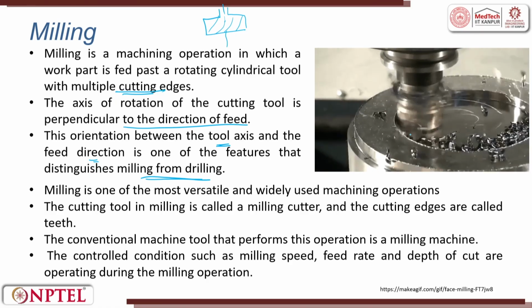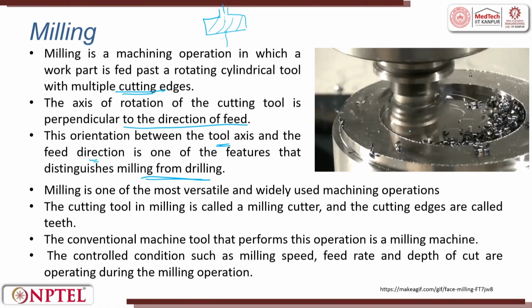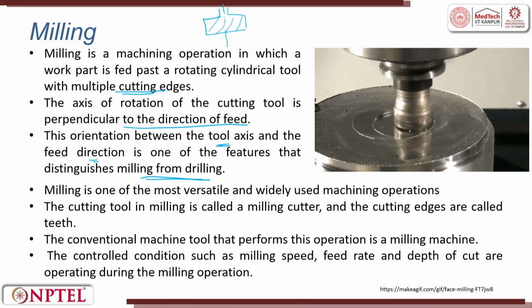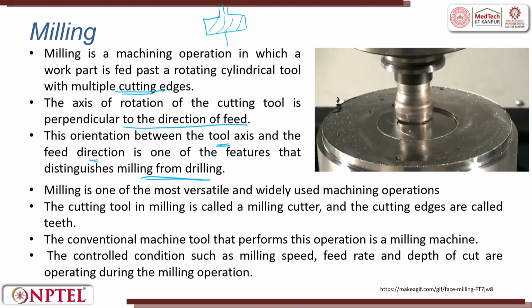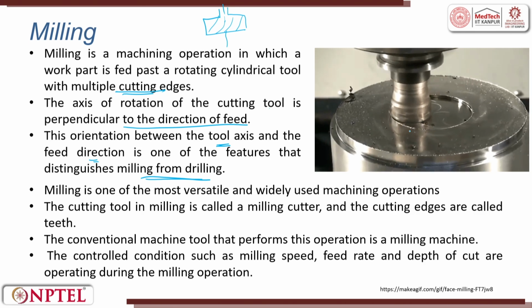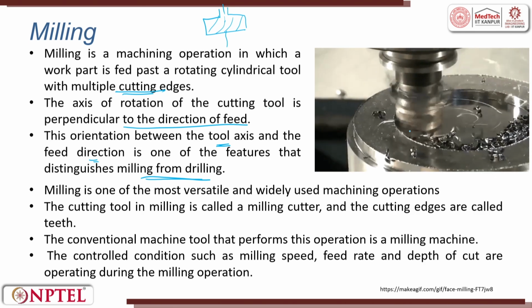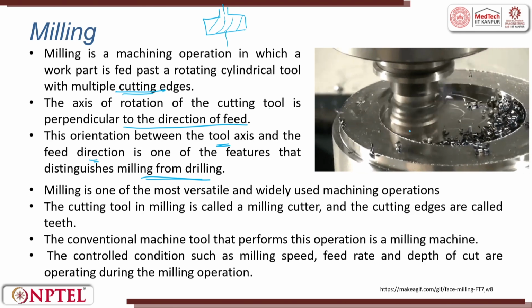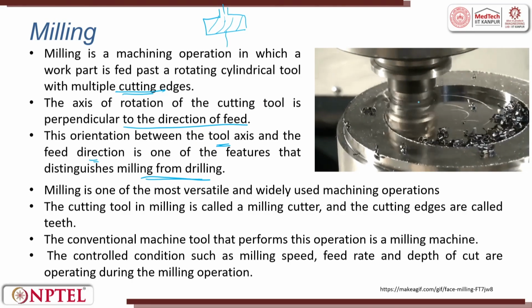We saw the drilling operation using a lathe machine, wherein in the tailstock we mounted a drill and then rotated it against the workpiece. So, there the RPM was given to the workpiece and the drill was advanced by hand. Here it is given by the machine tool.